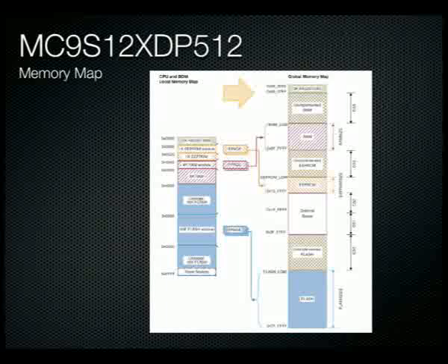And in part of that last 16K unpaged flash section we have a 2K read-only portion. It's write protected, currently contains a serial monitor, and there's no way in the world that we can currently change it without having a BDM pod that allows us to erase it. So under normal operations, we cannot erase the highest 2K of our flash.